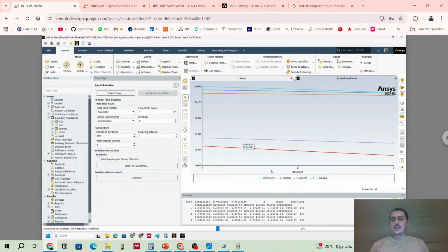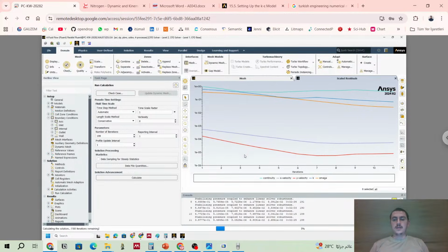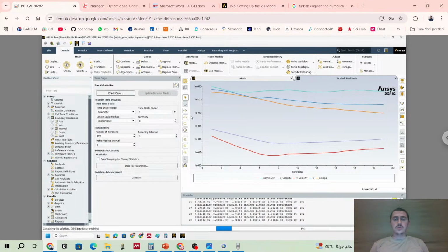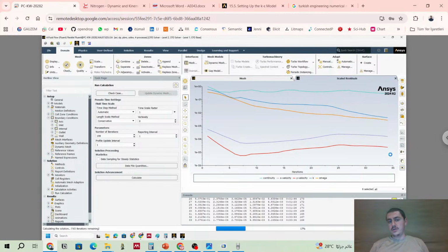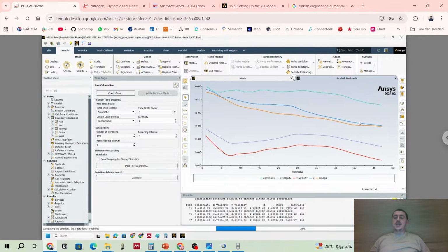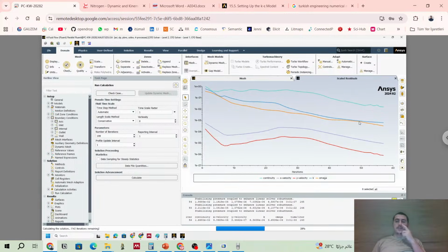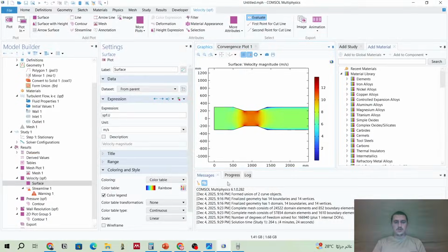And you can monitor your solution, how it goes, by the convergence, the iterations and the error shown here on the other axis. So it should go down and converge. But if there is a mistake in the mesh, or in an unphysical case you defined, it should not converge. But I'm happy that alhamdulillah it's going good now. So let's see if it's converging, if it's going well. Let's see COMSOL. Let's see our friend if it's comfortable. I think everything is nice.